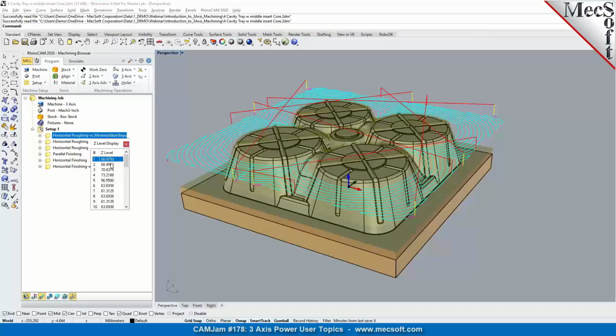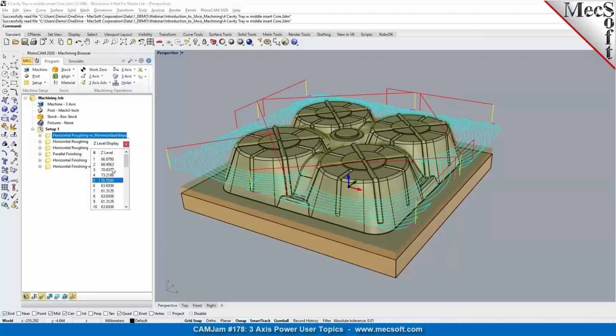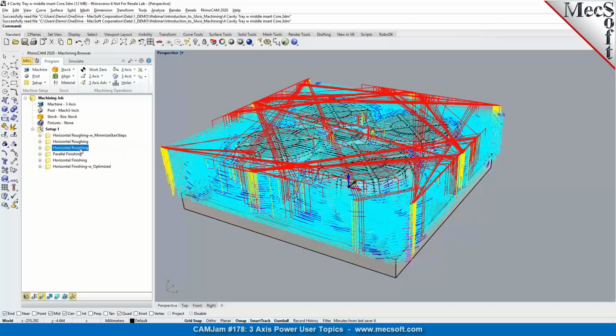You've already cleared out a lot of material, and now we're using that in-process stock to only go in and whittle away the amount of material you haven't removed in the preceding Z levels. So it is quite different from using a much smaller delta Z and machining the entire stock model. Because if you're doing that, you're actually cutting the entire stock model for each delta Z. That's a significant increase in the number of toolpath points. That's what Uday is pointing out.